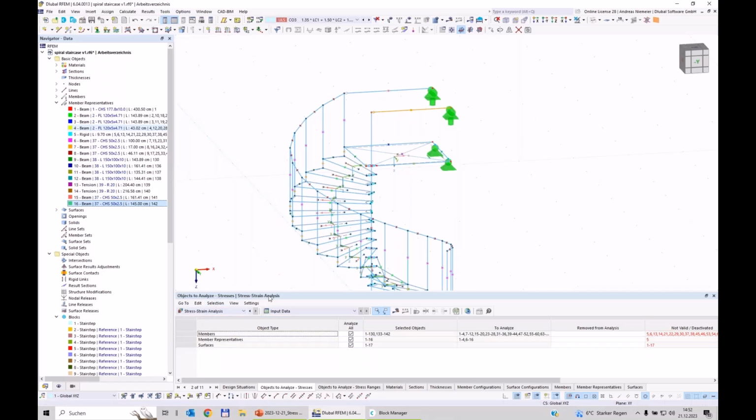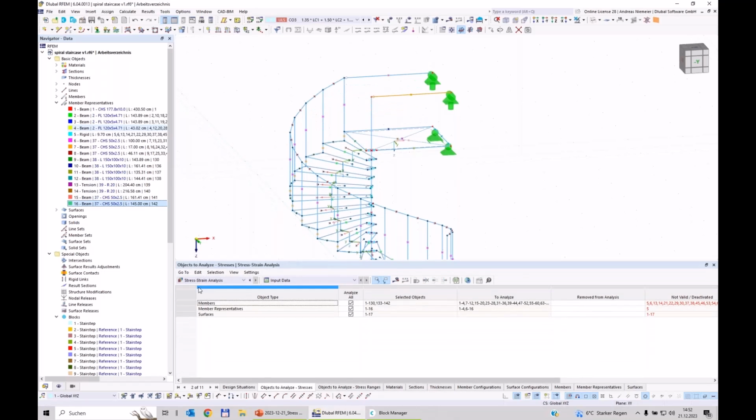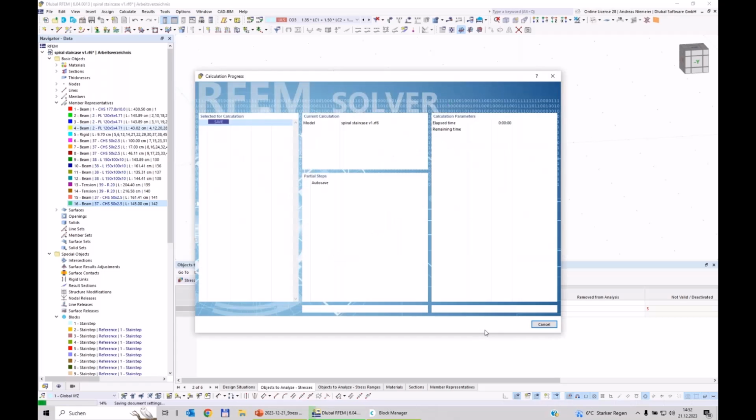And if we give the stress strain check not the job to design all members and surfaces, and only representatives, we get in the design finally 16 positions, which is nice to read for your clients. So you see, oh, okay, all poles of handrail, all stairway steps, whatever. So you have a clear grouping of elements and you design only 16 positions. And let's see what happens.